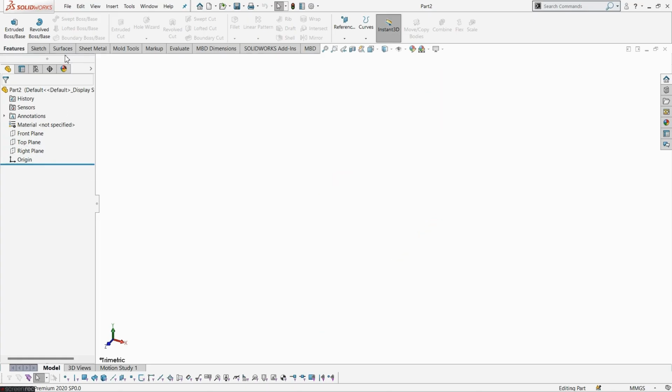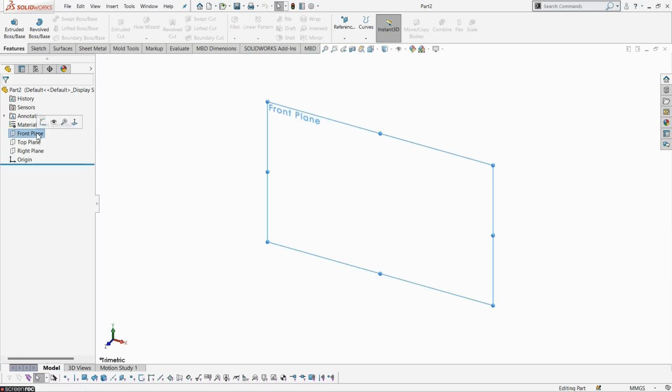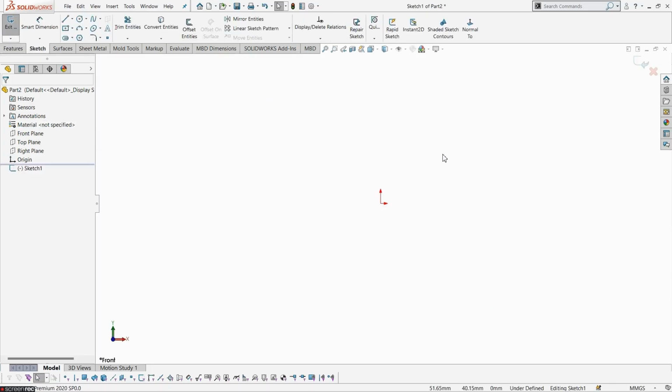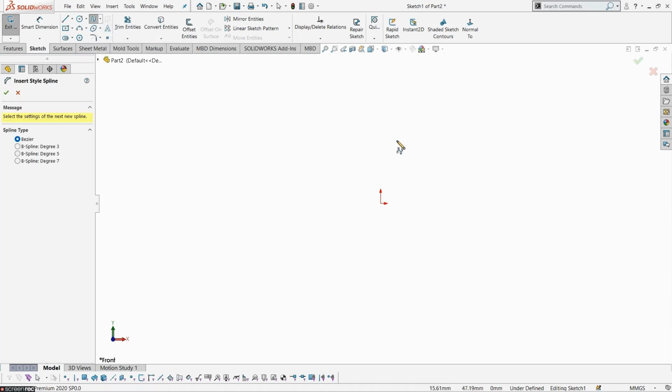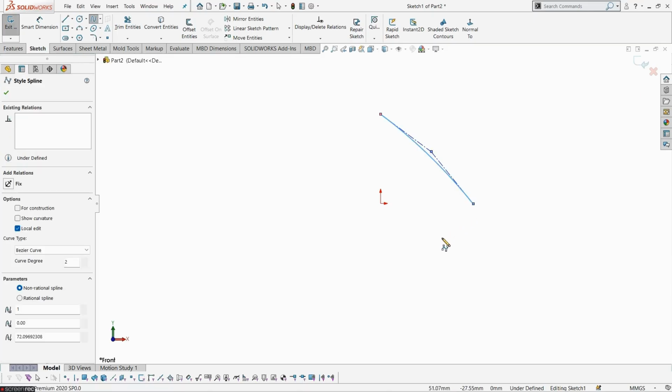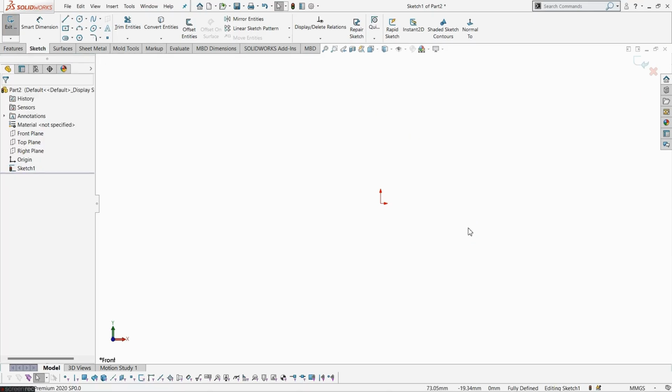Okay, let's select the front plane to initiate a new sketch from our drawing. Swept Boss is based on the path curve and profile, and we can draw the entire model with it. First, create a path curve. Using the sketch plane profile only, I am going to create this 2D sketch. So select a sketch plane, because only in the sketch we have Convert Entities. Using Convert Entities, we can easily modify an entire sketch.